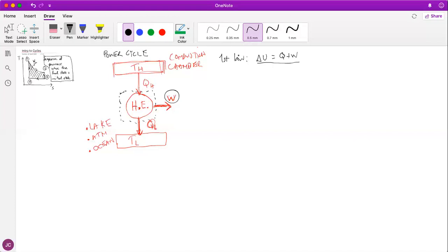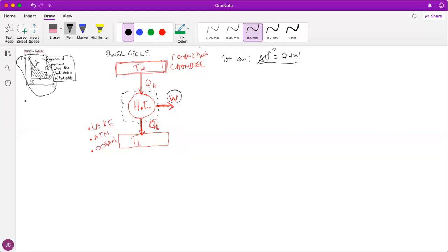Okay, fine. Now, there's also one catch. So this thing is zero. Why is delta of the internal energy, the difference in the internal energy, zero? Well, just because of this. I need to be more explicit about it, but I would say that after a cycle, delta T equals zero, delta U equals zero, delta P equals zero, or whichever delta of a property, volume, equals zero. They need to be zero. Why? Because you go to the same place.